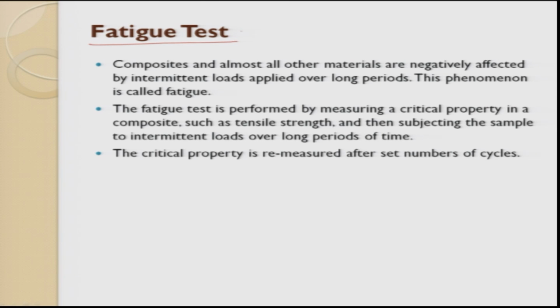Fatigue can be a compressive load, it can be a tensile load, it can be a combination of these, and when you do a combination it can change with respect to time and magnitude. So you can try several variations of this and then try to understand how your material is responding. So what are you doing? You are doing a dynamic study and trying to understand the behavior of your composite.